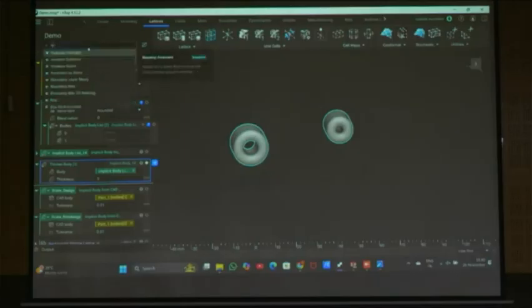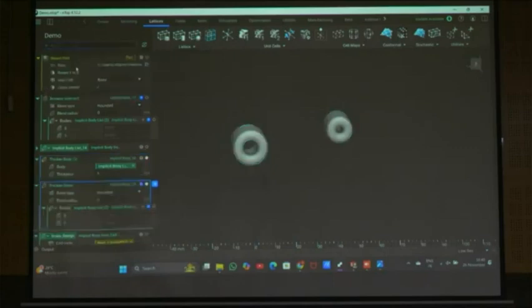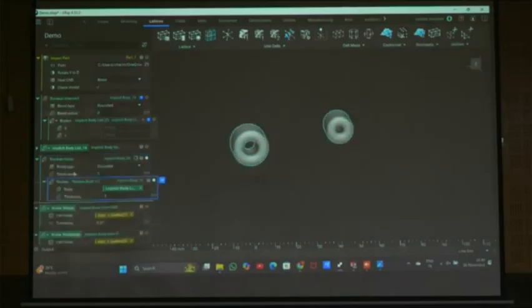So how to do this means, first I will take the Boolean union. I will delete this one, because this is as a single body. There is no primary body and secondary bodies. This is as a single body. Those three are separated. We need to take that in the single bag, right? So I will take this and delete it. I will drag this one, so that now this will be in the single body, okay? I mean the shape didn't even change. Now that can take it as a single body.